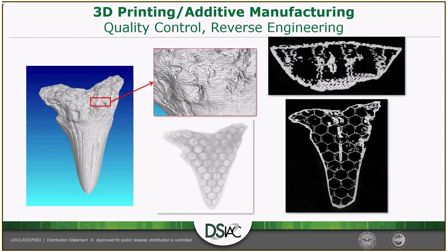This is a heavily used tool in the field of additive manufacturing right now, specifically for metals. With the laser sintering devices, if your powder is not getting sintered fully or you're getting voiding or different kinds of defects within your additive manufactured components, the CT scan can actually tell all of that based off density. So if you're getting a lot of metal 3D prints done, it's not a bad idea to get involved with the CT scanning side of things and see, is the print consistent?